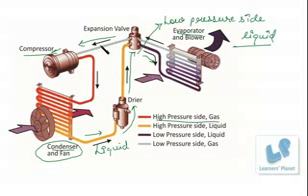First it is on the higher pressure side, from gaseous to liquid form, and then finally into the low pressure side in the liquid form, and then it will convert into gaseous form again, and all the heated air or the hot air will be blown off via the evaporator and blower. So this is the very simple mechanism of a window AC.